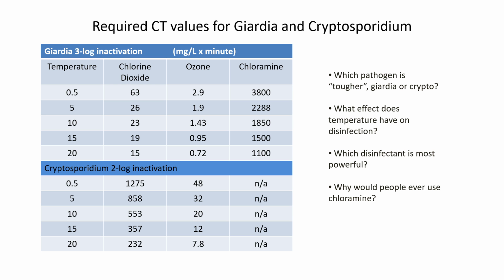So it's some organic, meaning carbon-containing material, and so the water has a little bit of dissolved organic carbon in it. If you then oxidize it by adding a chlorine disinfectant, then it can form disinfection byproducts that are known to be cancerous to humans. So people would use chloramine for that reason.